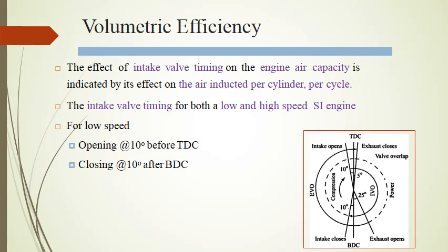Now, as shown, the intake valve starts to open 10 degrees before top dead center. It may be noted that the intake valve closes 10 degrees after bottom dead center.